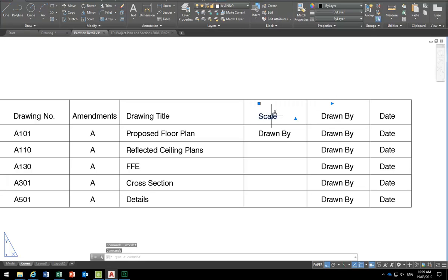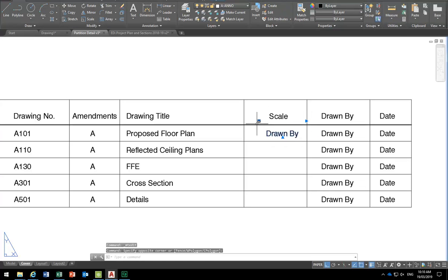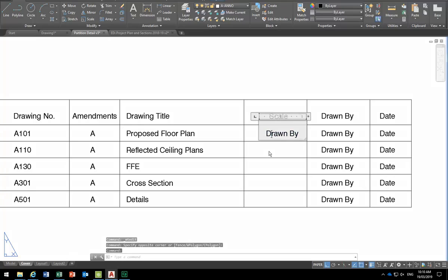And if you're not sure, you've got all the drawing options, also the text formatting option when you double click up the top there. You can justify it and make it center and so on. And so I can do that here as well. For some reason dragging to the left is always difficult when you're in that double click text editing, but when you just select it once, you get the grips and they work just fine. It's one of those strange AutoCAD things.